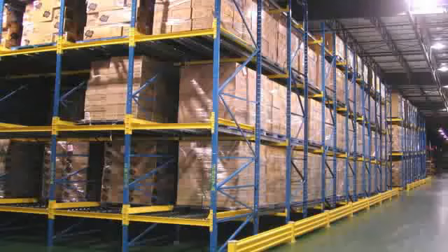And thirdly, they usually have a quicker throughput time for loading pallets and taking out pallets because you're always working from the service aisle. The way it works is once a pallet is put on position on one of these carts, when the next pallet is brought forward to load onto the rack, you just push the other pallet backwards and you keep loading in that fashion. The lanes for pushback rack can handle anywhere from 2 pallets deep to 6 pallets deep. When you start unloading pallets, it's kind of the reverse of the loading operation. As you take off one pallet, the next pallet or cart flows forward to the service aisle. So that's what causes the decrease in throughput time versus drive-in racks.